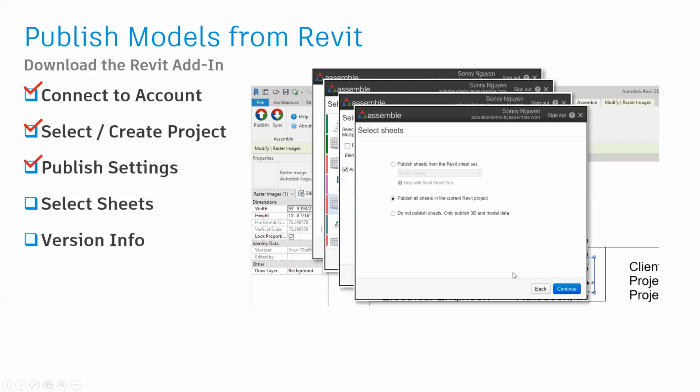Once I've done that, Assemble is also going to ask us if we want to publish any sheets from this Revit model. So we can publish sheets from the Revit sheet set. So if we have existing sheet sets set up, we can do that. In this example, we've got a room status sheet set, so we could publish that if we'd like. We can also publish all the sheets that are in the current Revit project, or we can publish none of the sheets.